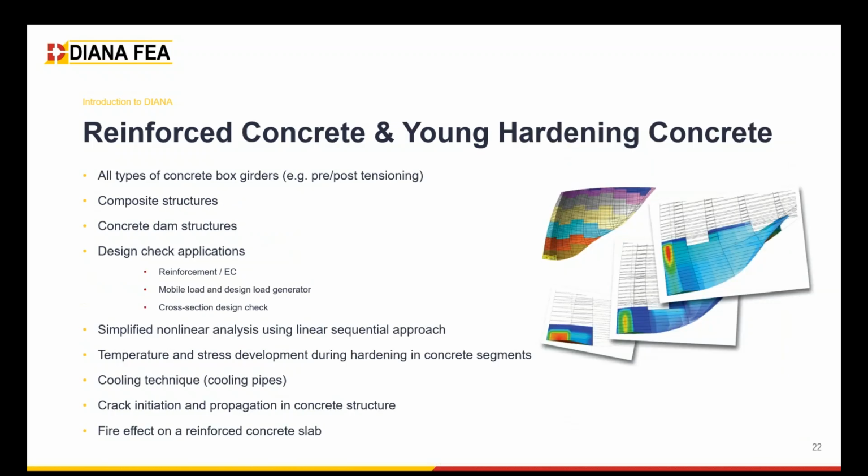Next to that, we have a very comprehensive solution associated with reinforced concrete and early age behavior of the concrete cracking. That's mainly when the model and the cast concrete go through the process of hydration. For any types of concrete box girder or composite structures, could be interaction of concrete with metal or combination of concrete with fibers.